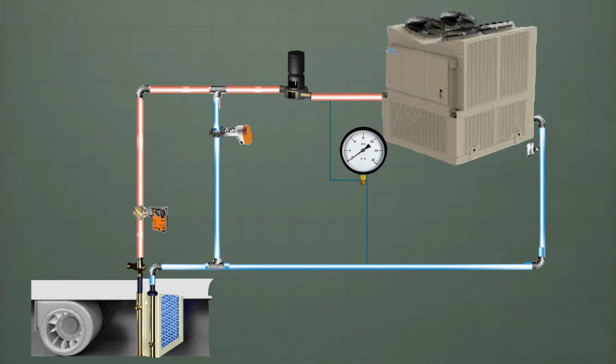So after you check your sensors, then go ahead and do the same with your transducers. Just gauge up to it with your gauge. It doesn't have to be perfect, like I said. Just make sure it's within a couple PSI, so that way you can trust the readings that you're going to be getting on the Microtech when you are troubleshooting.